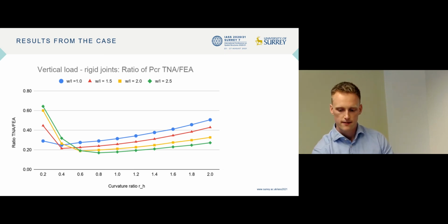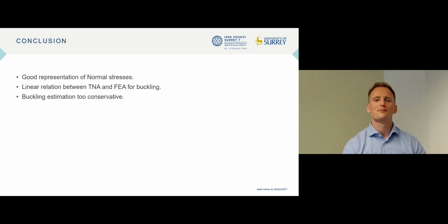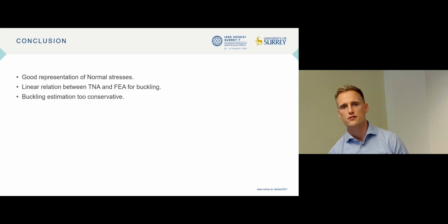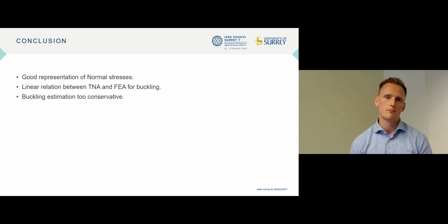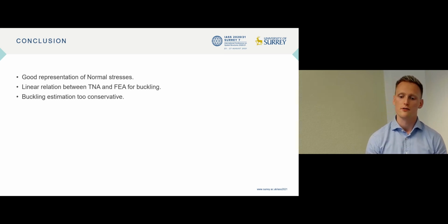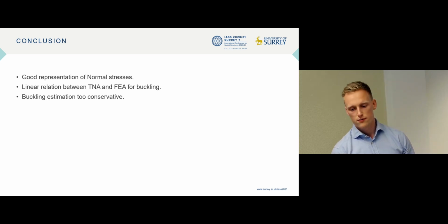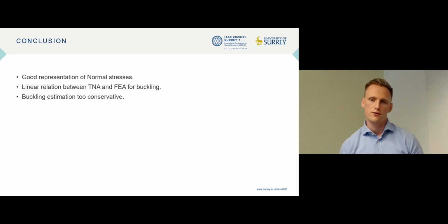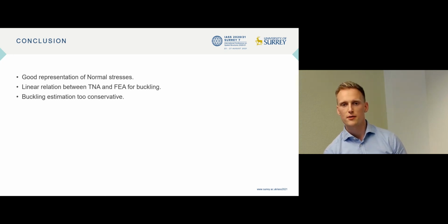To summarize, the proposed method shows an accurate representation of the normal stresses in the grid shells. Moreover, there is a linear relationship between the buckling estimates from the TNA and the finite element analysis, although for curvature ratios below 0.4, the results are not valid due to the lack of bending behavior of the TNA. So in the future, I would like to include cases with more diverse and complicated geometry to further investigate this. Thank you all for watching, and if there are any questions, I'll be happy to answer them.